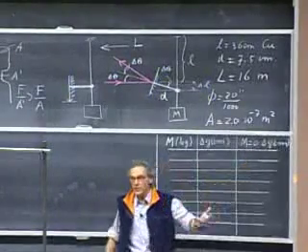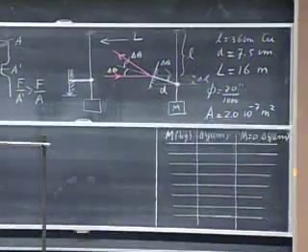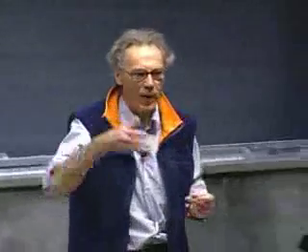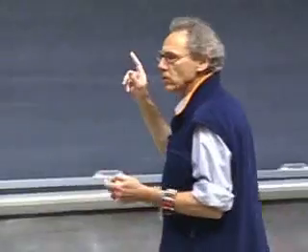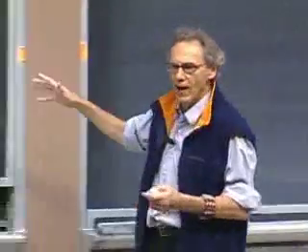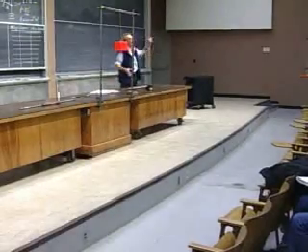And then in between increasing the weight, increasing the force, we will take the masses off to see whether they return, whether the length of the rod returns to the original length. And you will see after a while that you get permanent deformation, then it no longer comes back to its original length. In other words, the laser spot will not return to 0 on the wall, but it will stay higher.